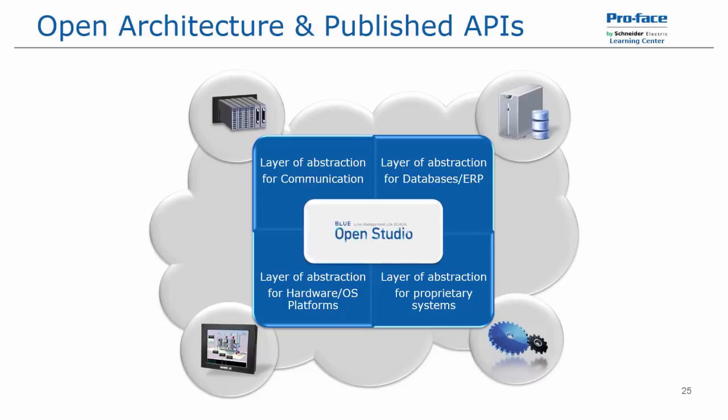With Blue Open Studio, all you would have to do is add the new driver, remove the old one, and then simply assign your new tags on the driver worksheet with the correct I/O addresses or I/O registers from the device. There is no additional configuration required, and there is no effect on the rest of the application. In fact, you could delete the driver entirely and the application would still operate normally, with the exception of no communication to a device. There are no errors, there are no issues.